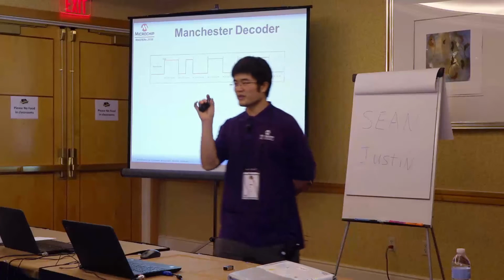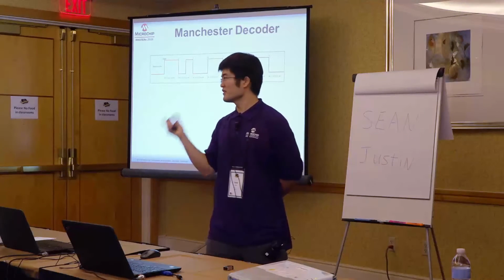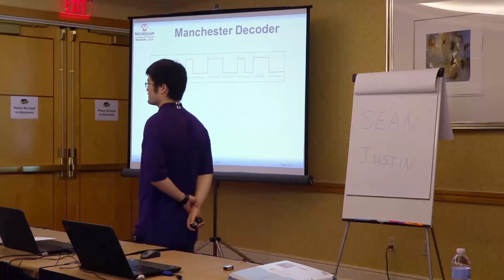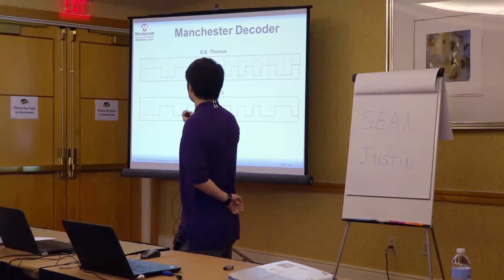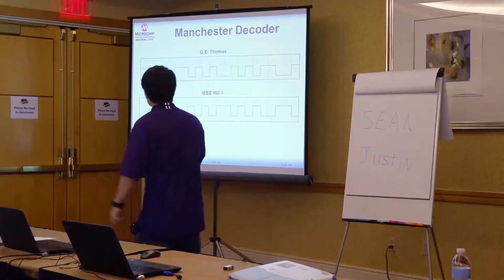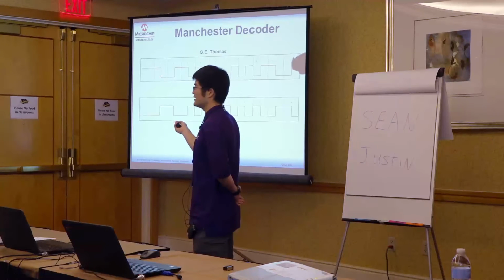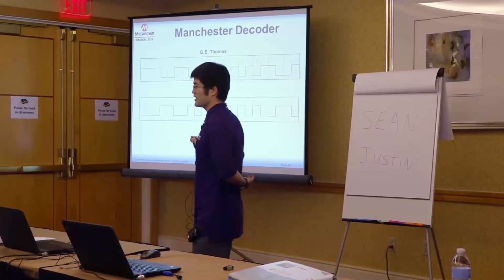So think about your bit time. Let's say it's 40 microseconds. We're using the first convention, so your logic 1 is the falling edge and your logic 0 is a rising edge. We call this a bit time. So this is 1 bit, and this is how much time it takes to see on the line.